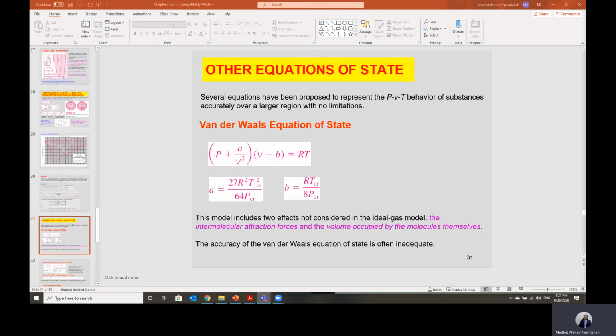And we agreed last time regarding your exam, because usually you ask about this situation. In your exam, you will assume any condition is an ideal gas, and you will apply Pv = RT directly, unless the problem asks you to calculate the properties using the modified equation of state Pv = ZRT, or asks whether this gas is a real gas or an ideal gas. That means we have to calculate the value of Z and use the modified equation Pv = ZRT in this problem. Otherwise, we apply the ideal gas equation of state.